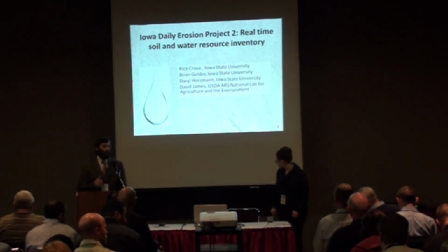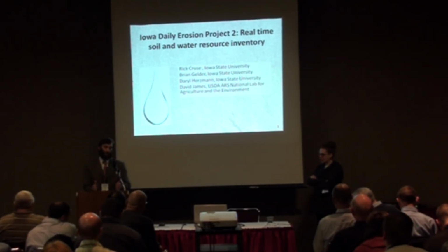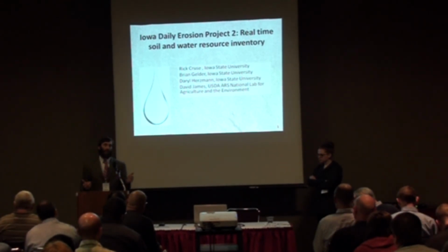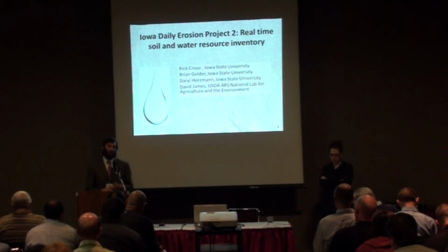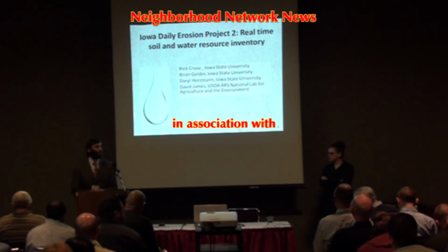In my experience, I've only used fly ash in the media. We looked at it a lot in the lab, but as far as actually building a structure with it, it was just a pilot filter. But same thing: not all fly ash is the same, but the fly ash I've looked at in Oklahoma actually removes trace metals. We build a lot of bioretention cells that use fly ash as the main media, and we're finding that they remove not only phosphorus but pretty much all the trace metals as well. Instead of being a source, they're binding it up. But again, you need to be careful with those materials and make sure you test them first. I'm not surprised at all by what you say.